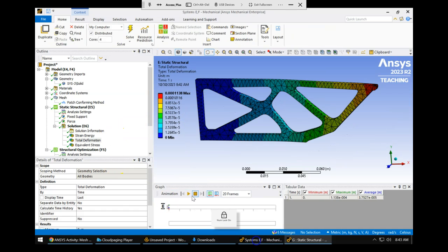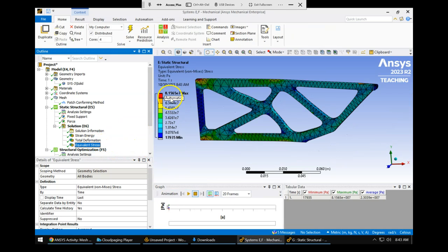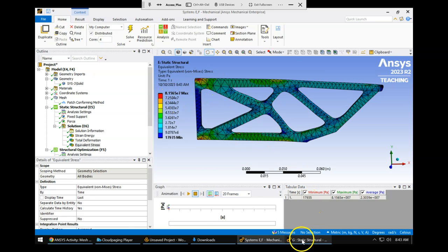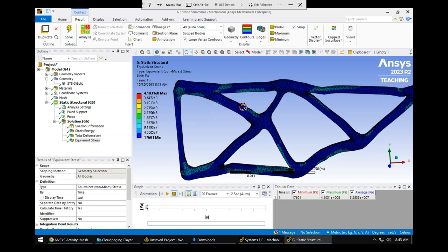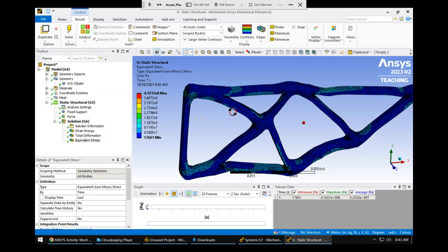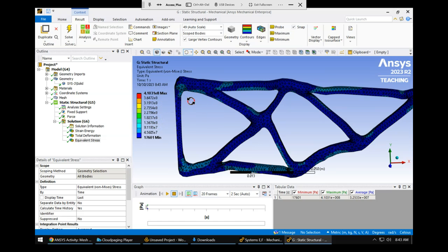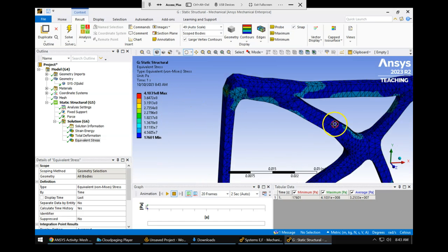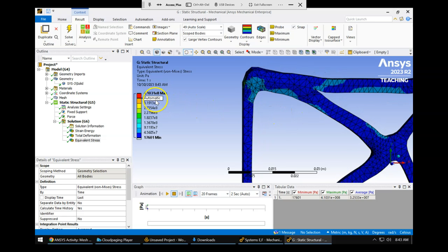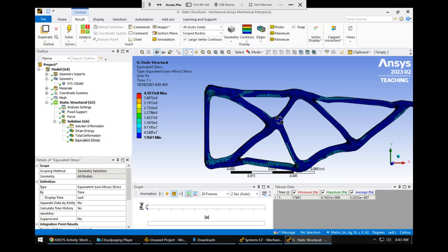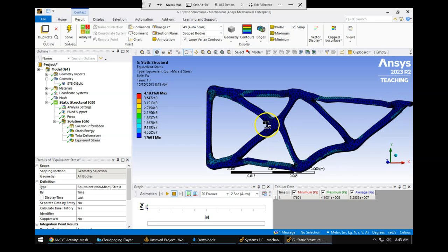We can also look at the stress. Previously we had a peak stress of 81 megapascals happening at the base. Stress is a little tricky in these models just because it's really sensitive to the mesh, and we get stress concentrations at the boundary condition. But here we're getting quite a bit higher actually. It could be a result of the mesh, and with the stress concentration at the boundary condition, it may not be realistic there. But it looks like it's 410 megapascals. But we weren't really optimizing around stress. We were trying to keep stiffness the same. So that allows us to check the results there.